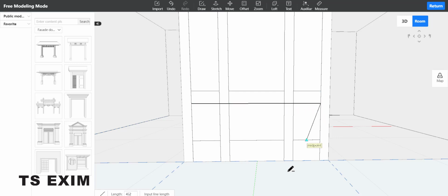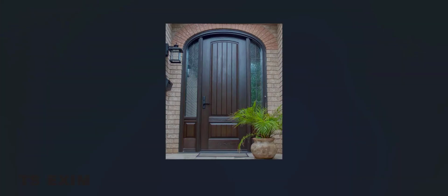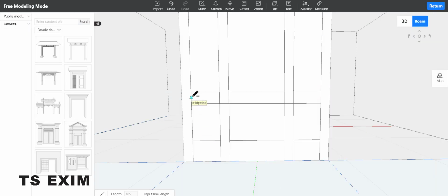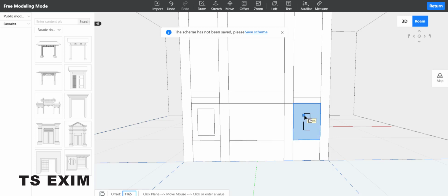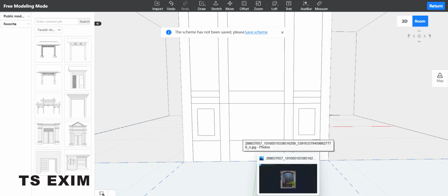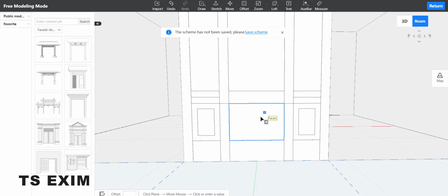And then add another line like the picture here. Okay. Divide the rectangle. Okay. Connect the midpoint to midpoint. Okay. Then I offset the rectangle to 60. Offset it to 60.